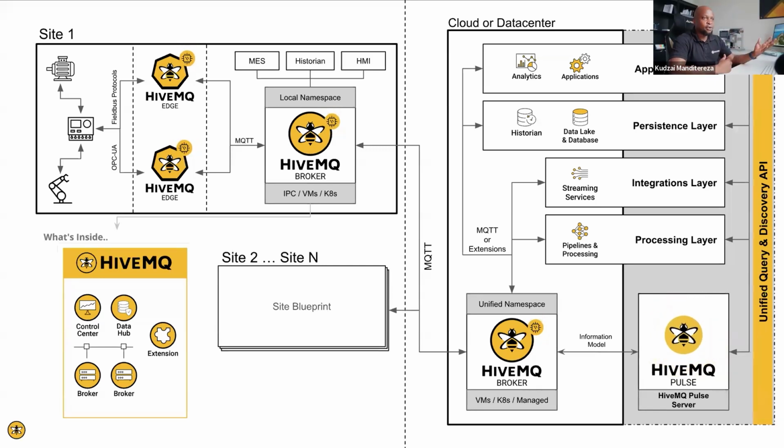So you've got data coming out of a Modbus device, data coming out of OPC, from a SQL Server database that you're bringing into Pulse. That agent then allows you to perform data contextualization, transformation, normalization, and aggregation within that specific real estate. That's why we talk about this idea of distributed data intelligence. You're not waiting until the data hits your cloud environment before you can generate insights off of it. And this intelligence is also available at a site level within the MQTT broker platform.